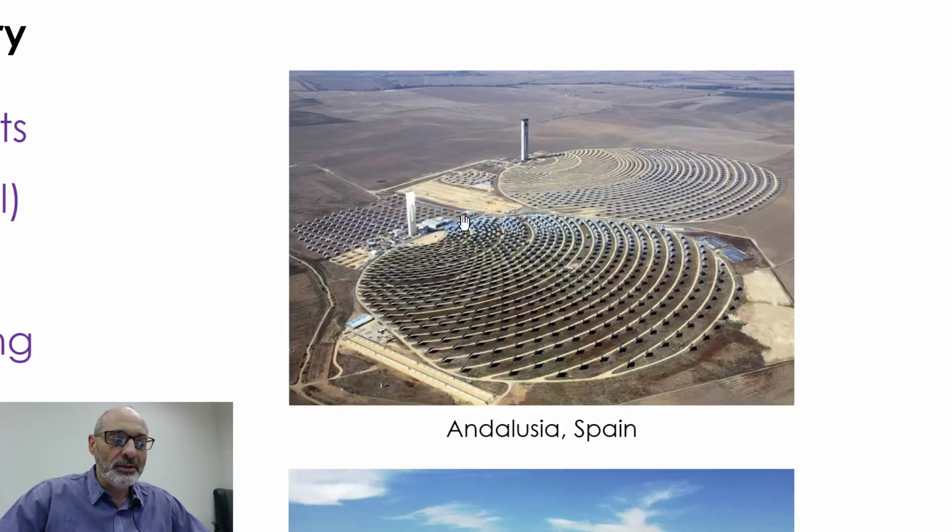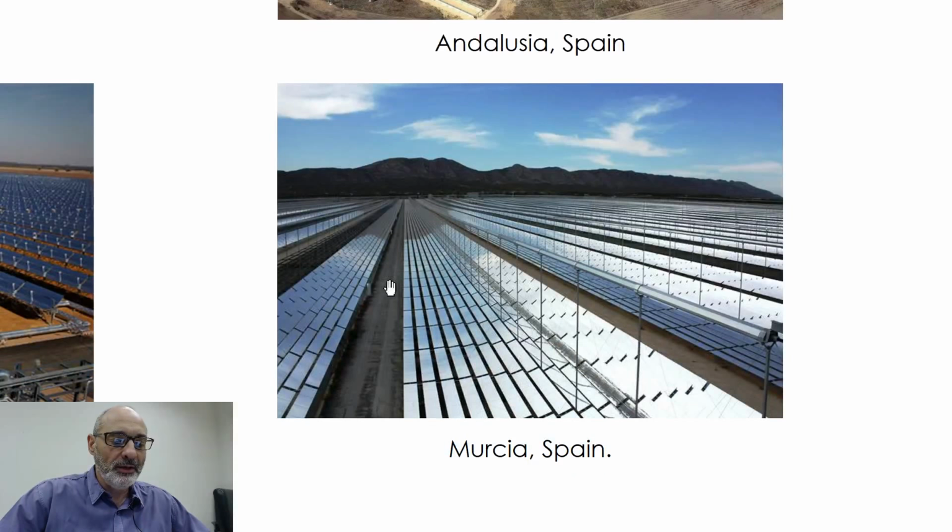So in the solar tower, all energy is concentrated on a point, and in this situation, the solar energy is concentrated on a line. In this line you have a tube. Inside of this tube you have the working fluid of the primary. We're going to see this. The Fresnel system uses flat mirrors that are able to move individually in order to focus the energy on this line.